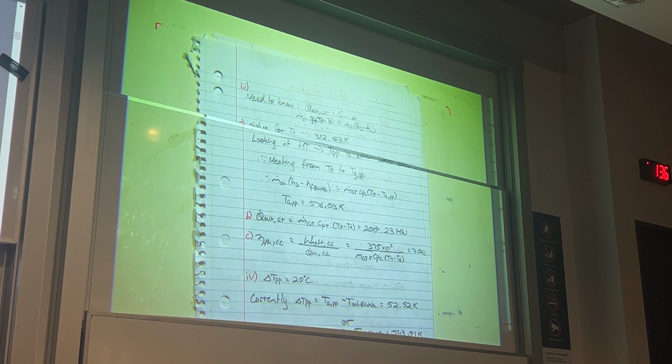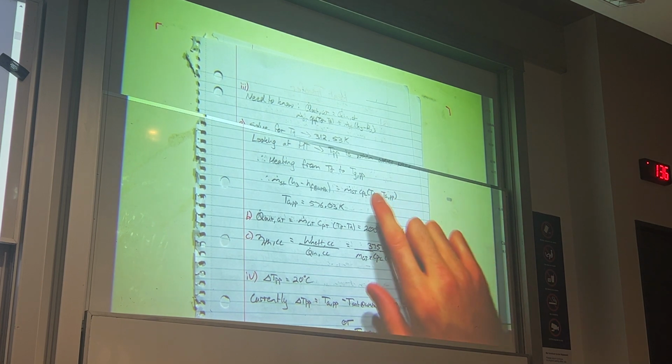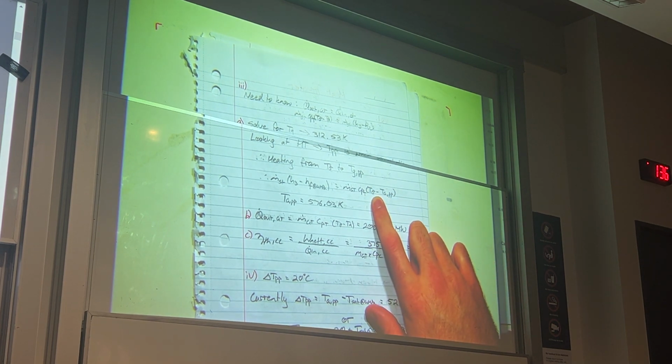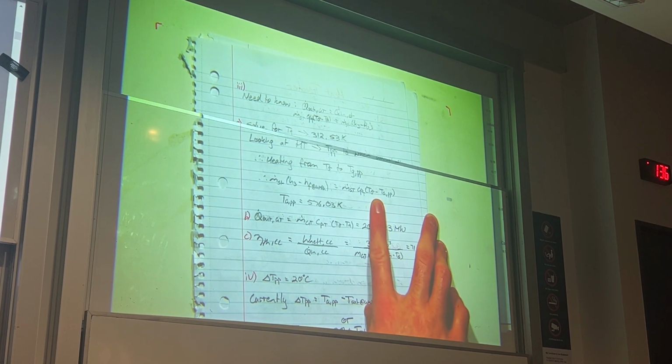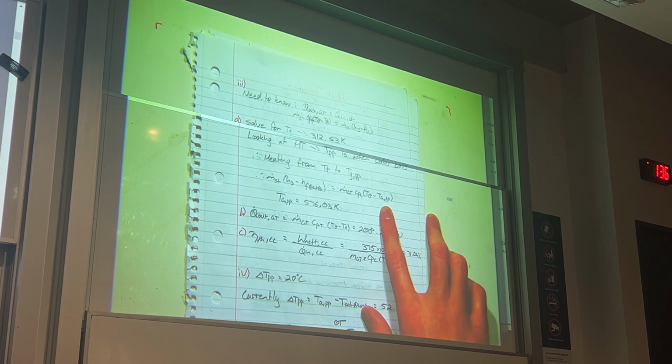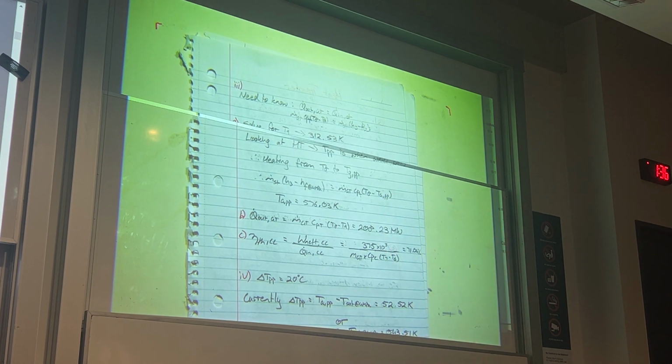So it's a saturated liquid, and then it's between temperature 8 when we enter our heat exchanger, and then the pinch point temperature, because after that point, due to inefficiencies in the cycle, we can't reject any more heat to our Rankine cycle.